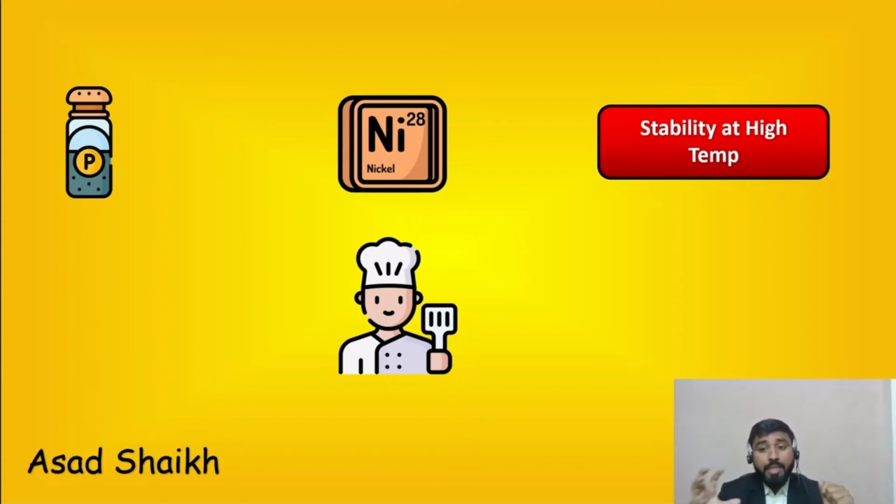Another important thing is the trim material. According to me, do not be stingy on the trim material. Select the best, because the trim is going to experience the highest amount of velocity, dp, everything. So the trim material should be at least the same or higher than that of the piping valves. And on trims we will go in depth hopefully in coming sessions, but definitely that material selection is very critical.